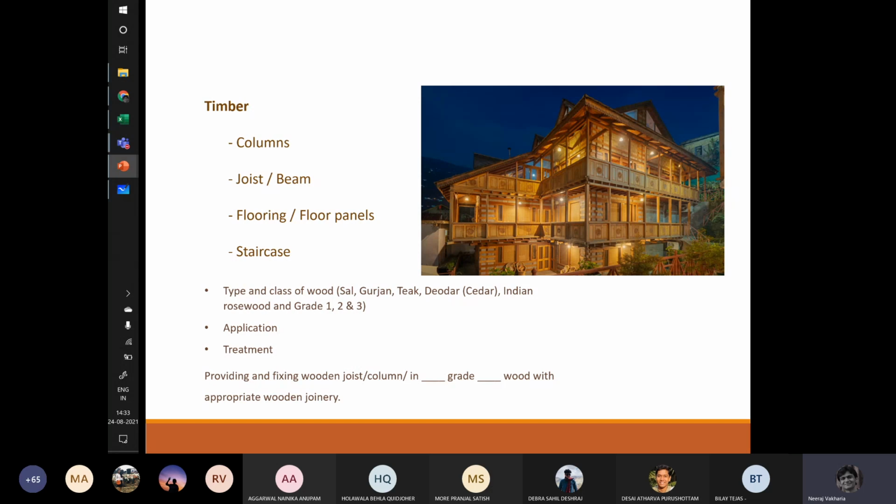And also the measurement sheet, whenever you write in your measurement sheet, keep it clean and clear. If you want to separate it out for first floor, second floor, do that. If you want to separate the sizes and write accordingly, then do it that way. Because changes might happen in your structure as you go ahead and discuss with your guides. If there is a change and you haven't clearly written in your measurement sheet, you have to find each and every quantity to check if it is correct, exactly which quantity it was and on which page it was. It's better you write your measurement sheets clearly, neatly.